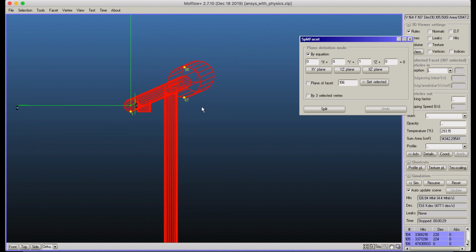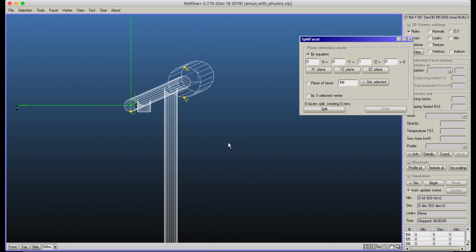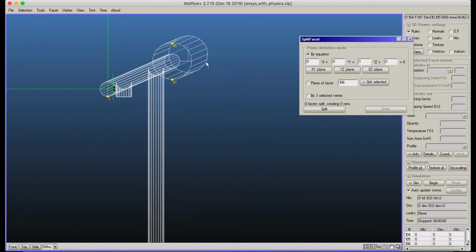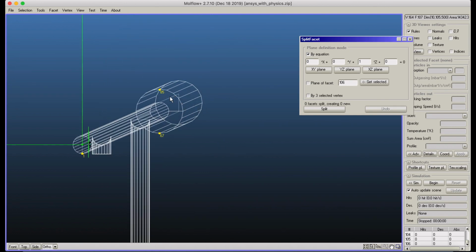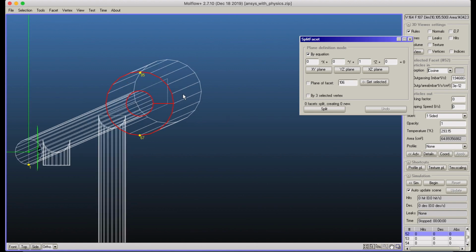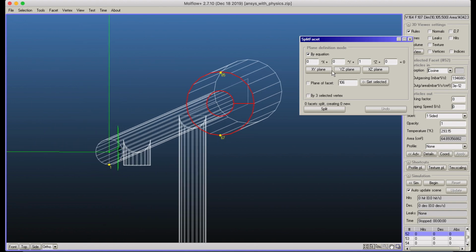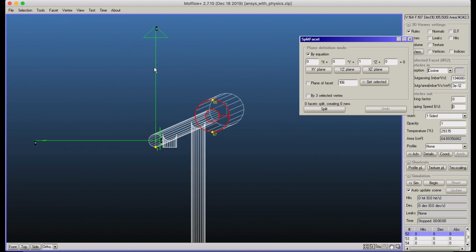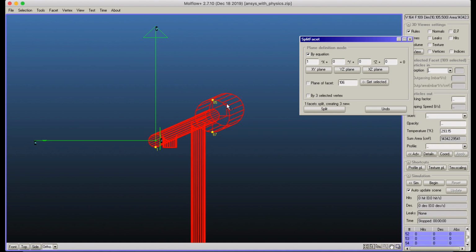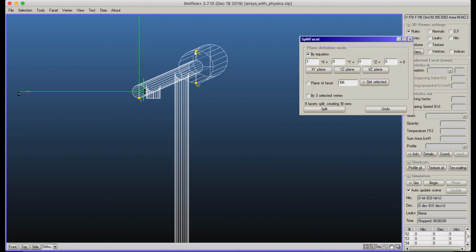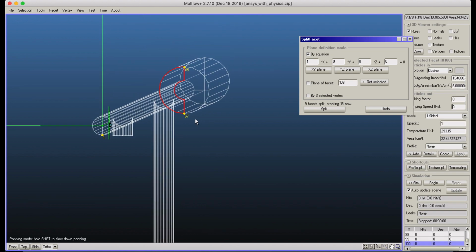At this point, I'm selecting all the facets, I'm doing a splitting, and okay, there seems to be, let me check again. Yeah, actually I don't want to cut by the XY plane, which is this one, but the YZ plane, so I made a mistake. Yeah, this is cutting. Let's select everything again and do the splitting, and okay. So my geometry has been split. All those facets that were crossing the plane now have been cut in two.